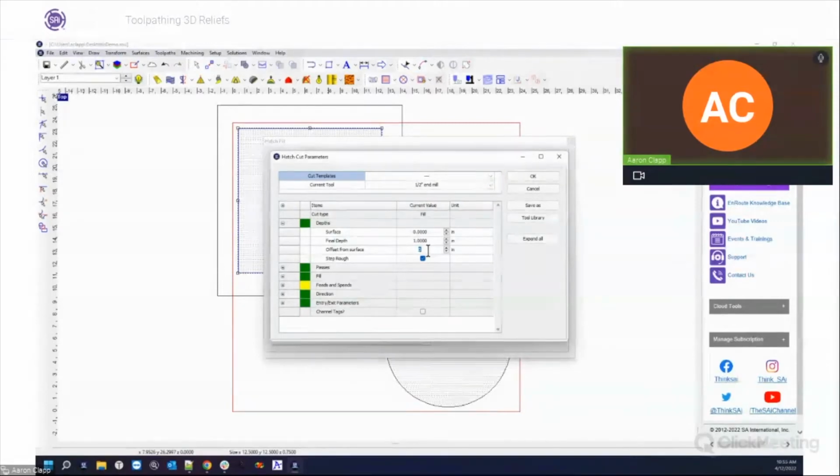Then I'll cut that later when I do my finish pass. I want my surface to be nice and smooth, and I don't want any tooling marks from my end mill. So I'm going to set a surface here, and this could be anything you want it to be, greater, larger, or smaller. Let's just go with 0.025, and then we'll click OK.